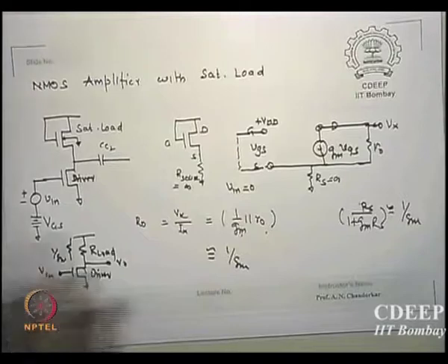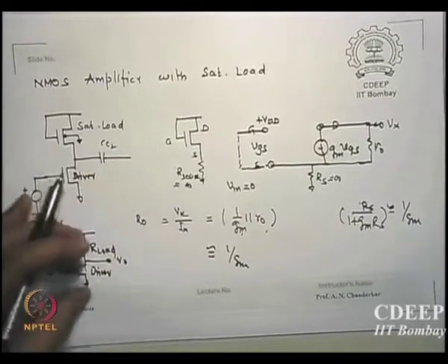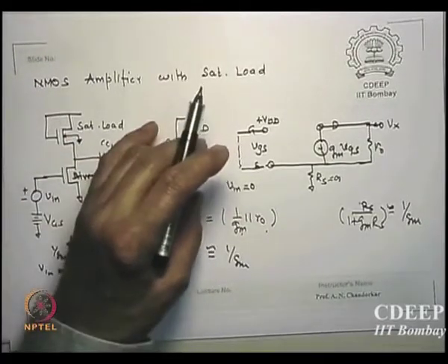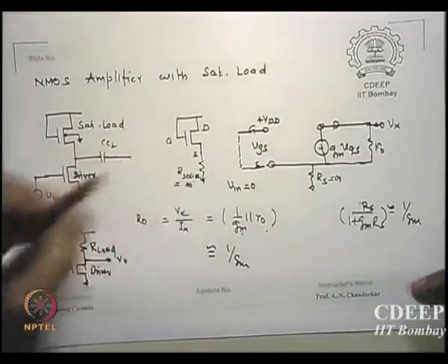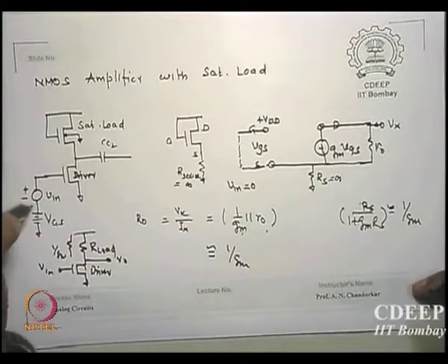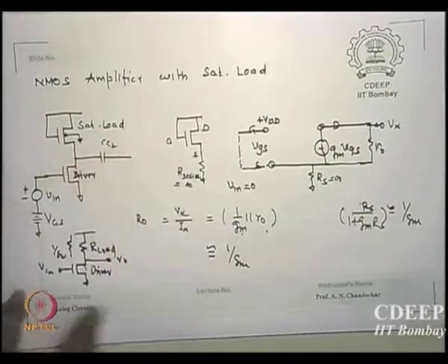हाँ, थोड़ा मैंने यहाँ थोड़ा सा हिंट दिया है ना. This driver acts like a series resistance for this amplifier or this transistor, and since there is no current will flow because Vin is going to be 0, this is equivalent of infinite resistance.